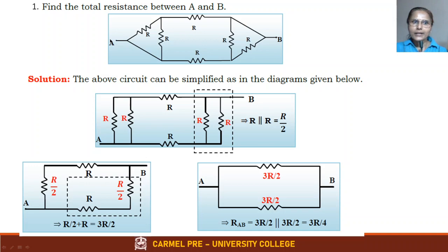If you think of current flowing from here, it gets divided, correct? And this point is the same as this point. If you come up here and see, this point is the same as this point. So that means these two resistors are in parallel. Similarly here also, this and this point are the same, so that means these two are in parallel. So this circuit can be rewritten like this: these two in parallel, these two in parallel, and these two remain as they are. When they are in parallel, it is better to simplify them into one single resistance.